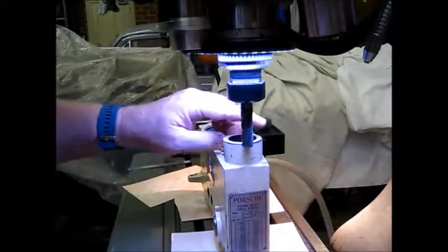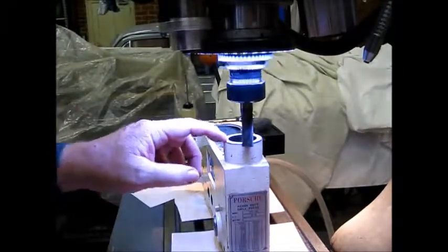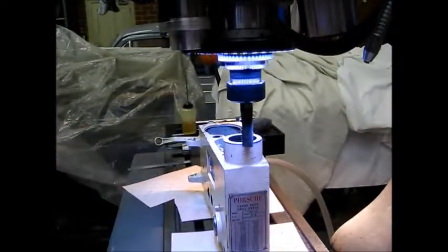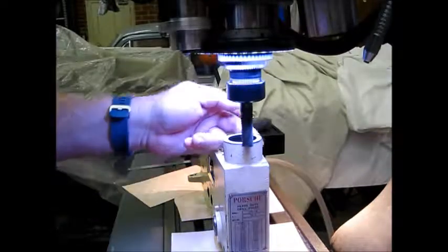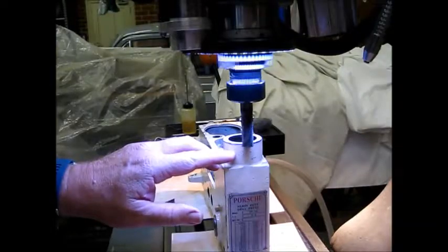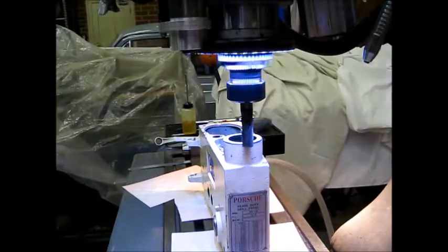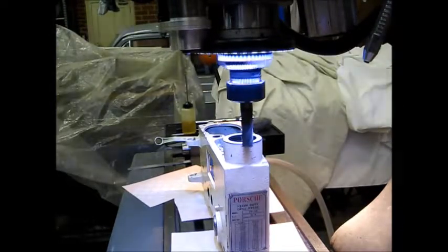I'm quite happy with the look of that. It seems like we're picking up a nice parallel cut around there, missing half the back of it, but let's just complete a deeper cut now down the face here. And I'm going to just plunge down from where I am, perhaps another 5mm, it should be fine.